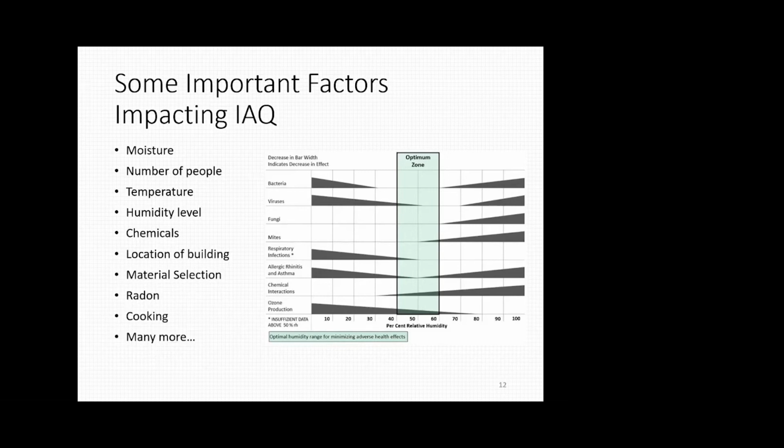So there are building materials like in cabinets, you get OSB, pressed woods, some of this synthetic stuff. Some of these things have formaldehyde in them, and they will off-gas. When you go into a house right after it has just been built, you smell it. Paint will off-gas. And this stuff is typically not very good for you. You don't want to be smelling this stuff. And if you can smell it, you're breathing it in. You definitely don't want to be breathing this stuff. So there again, ventilation is key.